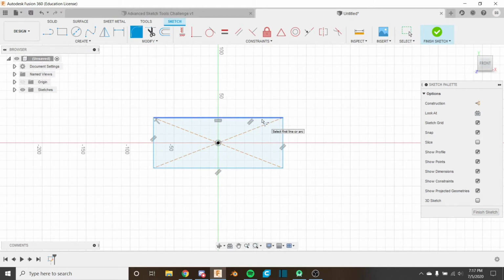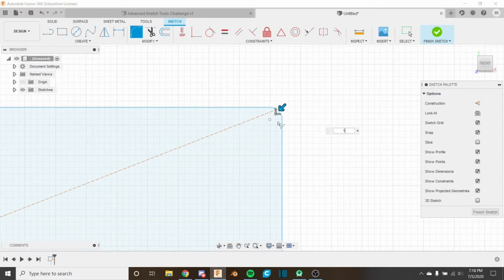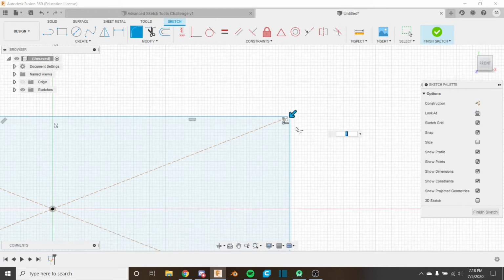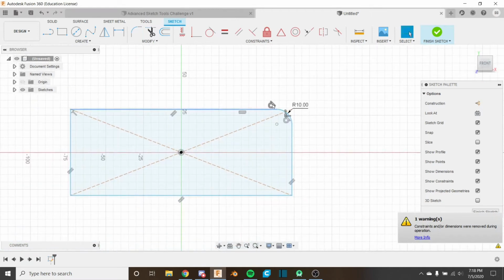It works just the same for an arc and a line, but I'll show you something that you have to be careful of in just a moment. So we select these 2 lines, and you'll notice it gives it a rounded corner. And this rounded corner is created by having a circle at this point here, and it's getting rid of the edges extending here and making this rounded edge, which is a circle. And the distance here is the radius of the circle. So if I change this to 1, let's say, then the radius of this fillet here will be 1. So I'm going to keep that 10 for now. We can just see how that looks when I press enter, and it gives it a nice rounded corner here.